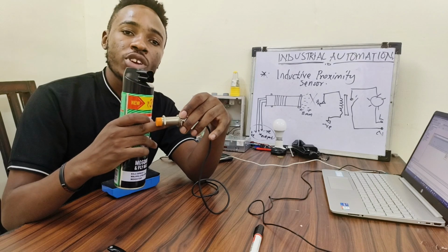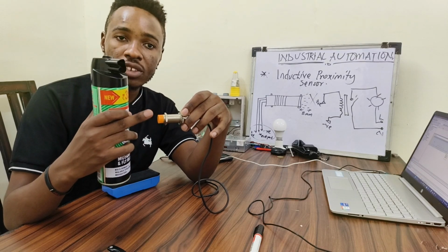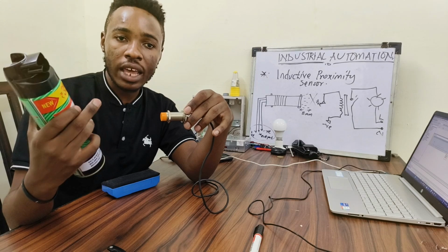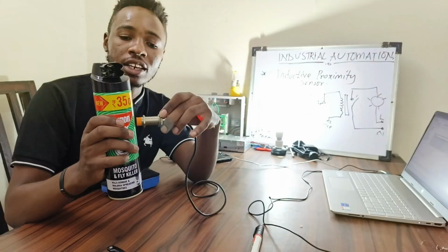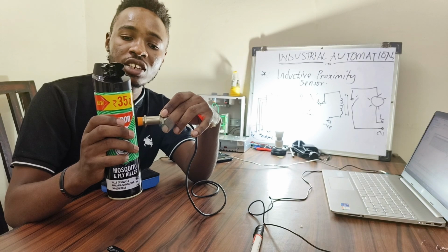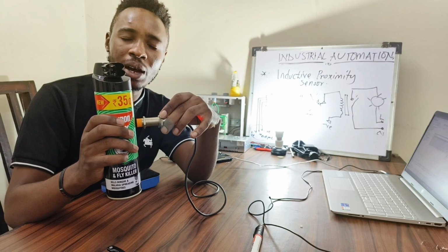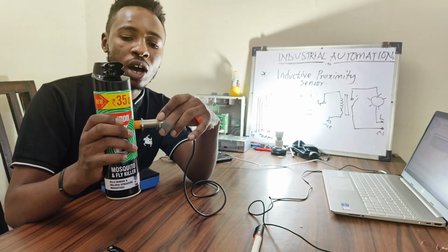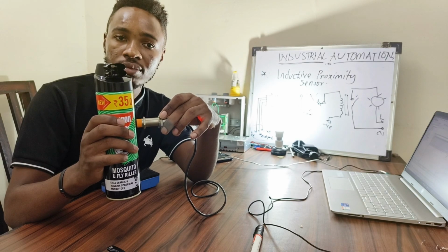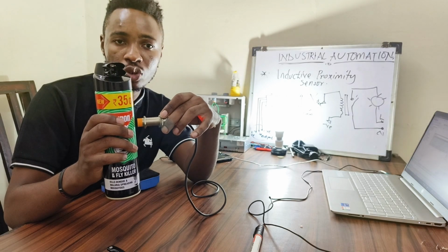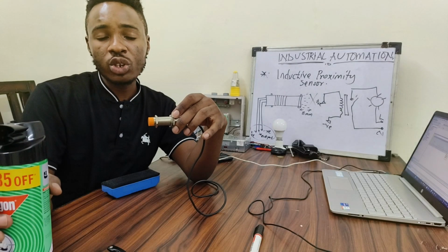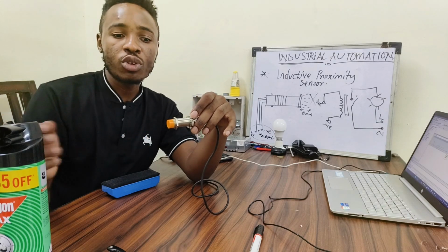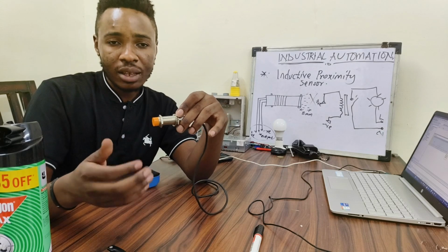And when it reduces, the trigger circuit will check the amplitude of the total flux that is being generated over here, and once it is lower, that's when you get the output signal. So if I do this, that means the amplitude of the magnetic flux in between is lower, and once it is low, the trigger circuit gives me a signal outside. So the advantage is you don't need contact. That's one of the advantages, which leads to a long life. So based on the application, you look for maybe a larger sensitivity area. So if you don't want objects to be much closer, something like that.